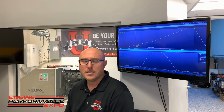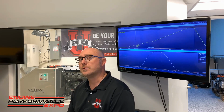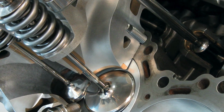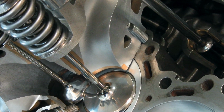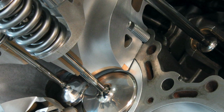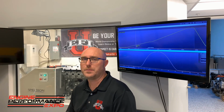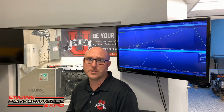For example, the most common use of the Spintron is to develop a better valve train. If you think about what the engine's doing, we always say the engine's an air pump. We've got to open the valves to get air in. We've got to close the valves and keep them sealed tight while we do our combustion process. Then we've got to open the exhaust valve and get it all out. The timing of those events, when they happen, where they happen, how quickly they happen, have the most influence, or the signature, if you will, on how the engine actually behaves and performs in real life.